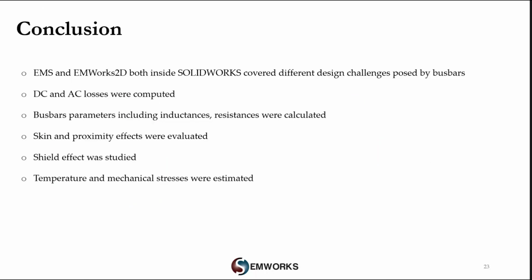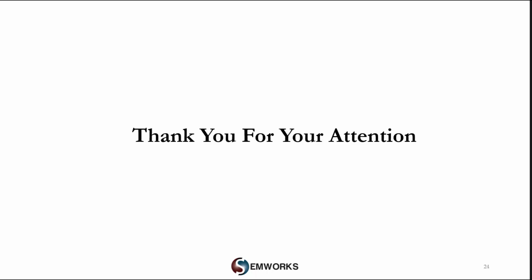To summarize, EMS and EMWorks2D, both inside SolidWorks, covered different design challenges posed by bus bar applications. DC and AC losses were computed. The bus bars' different parameters including inductance and resistance were calculated. Skin and proximity effects were evaluated. Shield effect was studied, and finally the temperature and mechanical stresses were estimated. Thank you for your attention, and I hand over the screen again to my colleague Carl to continue the presentation.